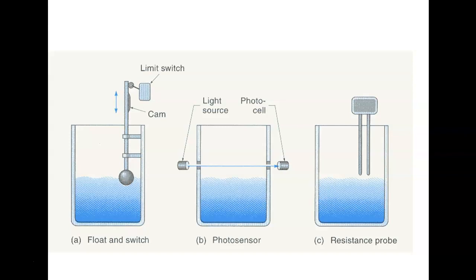Because this is a resistive probe. This will have to go through an A-to-D converter. What it literally does is bring the liquid up into the two resistive probes, and then it just depends on the conduction of the material. There's very little material that doesn't have some conduction characteristics, especially liquids, right?